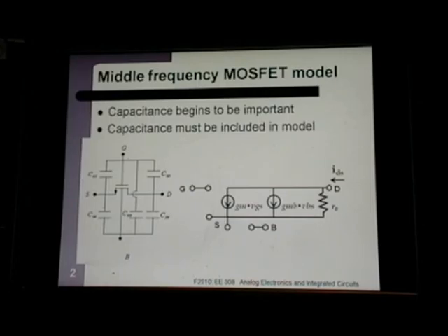So just to remind you, what we've done so far is we've sat on a node and we've looked around and seen what capacitance we see on that node, and then we've found the R on that node, and that's just the small signal impedance, and that was our R and our C. We took 1 over RC, which is the radians where there's a corner frequency on a Bode plot.